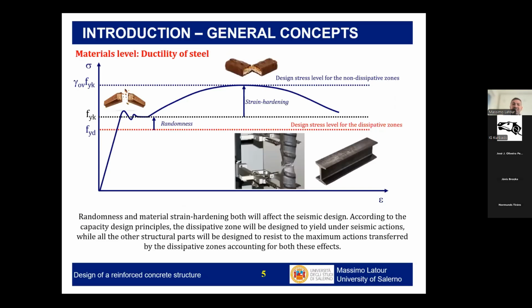Of course, in reinforced concrete, we don't reach high ductility of the cross-section, mainly because of concrete, but specifically we try to exploit the energy dissipation capacity of steel. So in concrete, this will be due to the possibility to have an elongation in a bar as large as possible. In a steel element, like a steel beam, this will be due to the capacity of the beam, so the deformation of the material which is composing the beam.